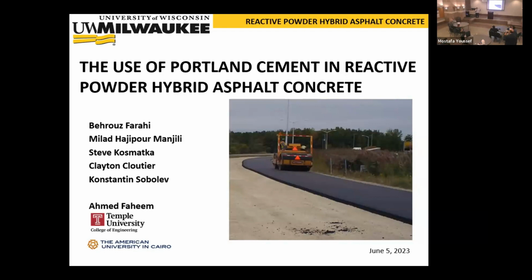This started with fly ash at the beginning. Yes, of course. That's how we started, and we built a few test sections. Fly ash is in between, at 5 to 6 OH groups per nanometer squared. So we are at the very beginning. If you were to optimize just for this kind of chemistry measurement, cement is a bad thing in the end. You should maybe go for silica containing large numbers of OH groups, and that will be even more reactive.